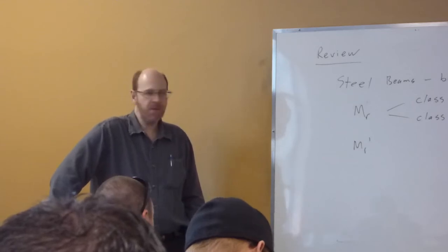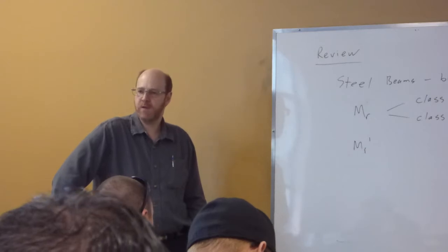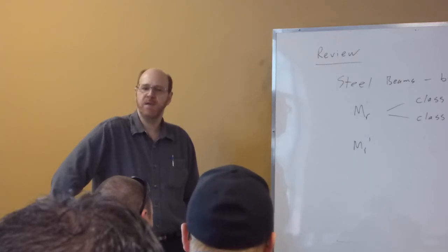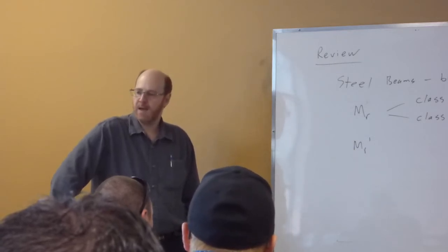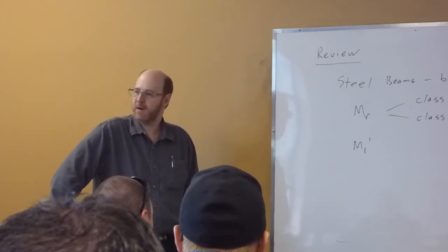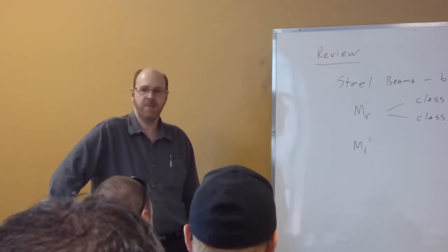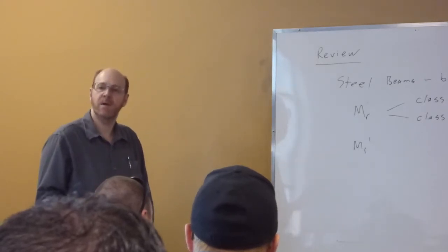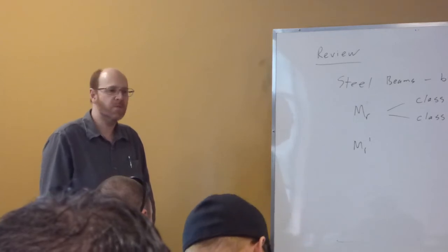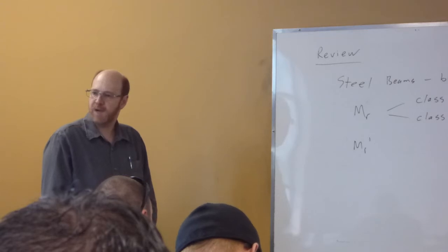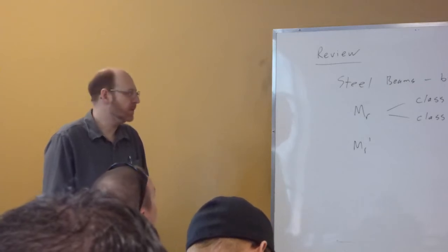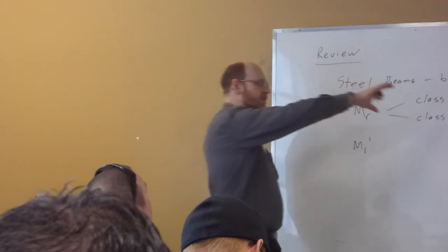Now there were some modification factors that we put on there, so rather than just MF over MR, depending upon whether it's a class 1, class 2, class 3 system, there's a slight difference in the equation that's used. We have a U1 term out in front. Depending on the equation, there might be a beta term out in front that needs to be calculated. And we also looked at what's called in the Steel Design Handbook lateral stability, which is our P delta check. So if we do have a scenario where the P delta effect could come into play, there's a multiplication factor coming from our U2. So that's applied to our moments.